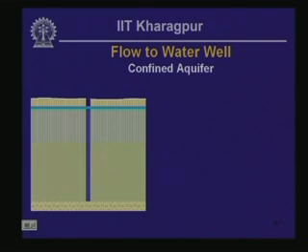In any case, the mathematical treatment is going to be the same irrespective of whether it is sub-artesian or artesian groundwater, and you can show by theoretical calculation for a homogeneous aquifer that there is a definite relationship between the quantity Q that you are going to pump out, or the discharge that you are going to pump out of the water well, and the reservoir or the aquifer properties and aquifer geometry, as we are going to see in the next little bit.